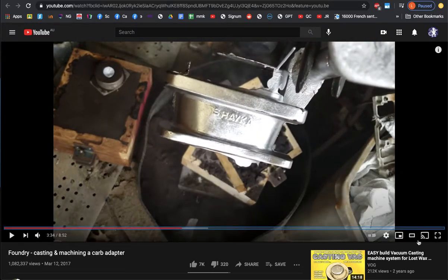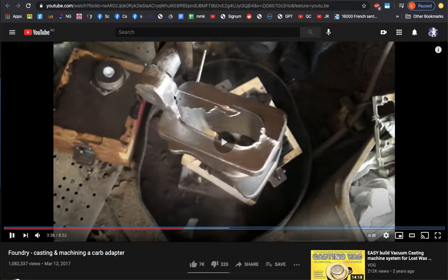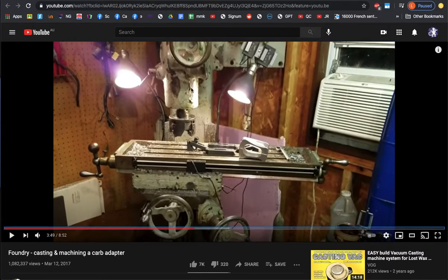Now, we can see along the side there's a flash line. So that line where we can see where the steel has been poured in, and we can see along the join. And that'll have to be machined to clean that off. Yeah, where the two halves have joined, and the riser and runner, they have to be cleaned off as well. So we can see where the metal's been poured in, that has to be cleaned out as well. Okay, so that's those two.